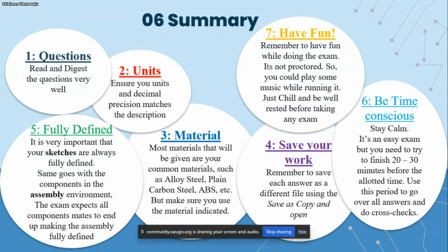Then save your work. Each answer, save as copy and open. Please always note that. Then number five, fully defined. Your sketch should be fully defined. Your assembly, not really, but sometimes your assembly must be fully defined.